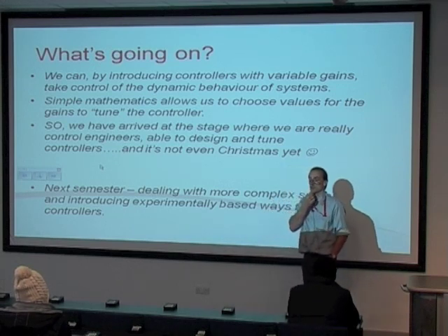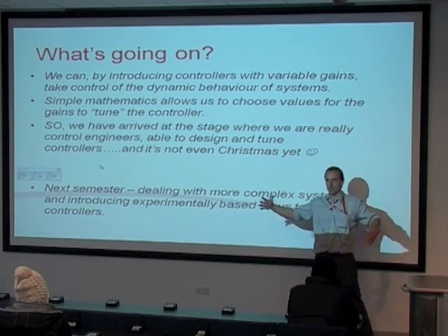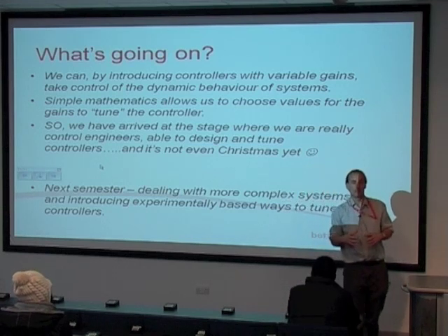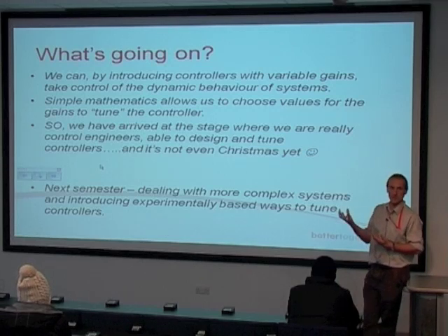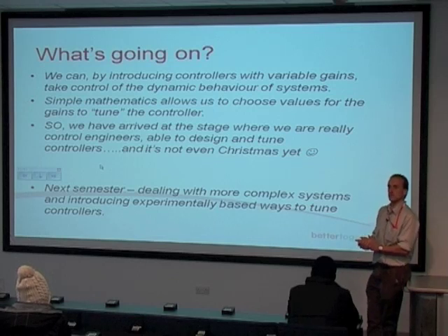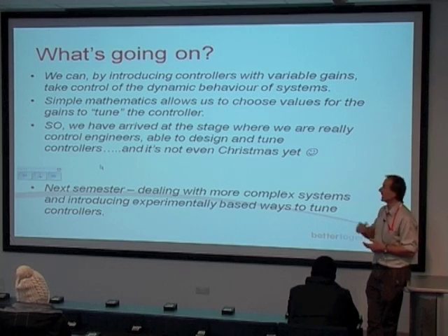The assignment will be out. And what we're going to do by way of an assignment for this module is again to try and pull all the things together, is a practical exercise in the laboratory where you're going to be controlling motor speed and motor position of a DC motor. And you're going to go through all those steps. The first thing you need to do is to actually find the transfer function of the plant. And you'll be doing that experimentally by measuring things. You'll be then given a set of performance parameters, and using these techniques you'll be developing a controller.